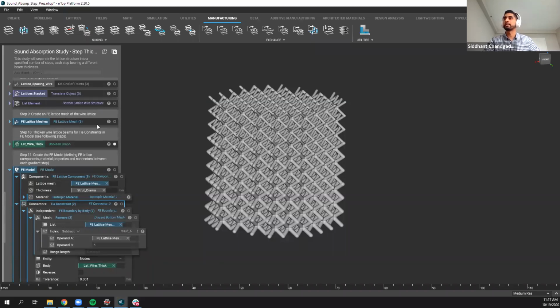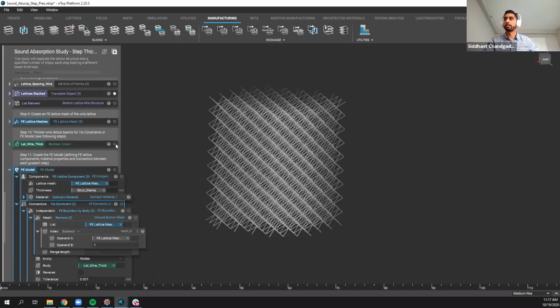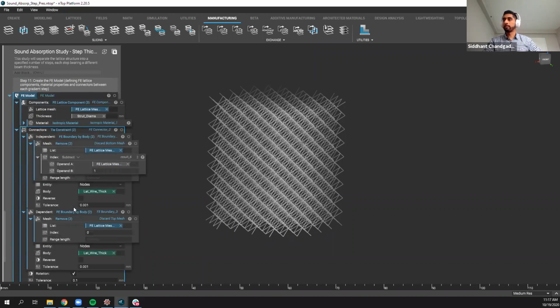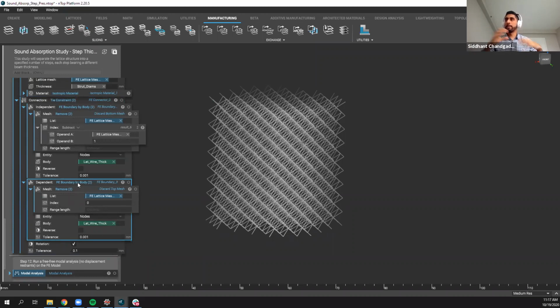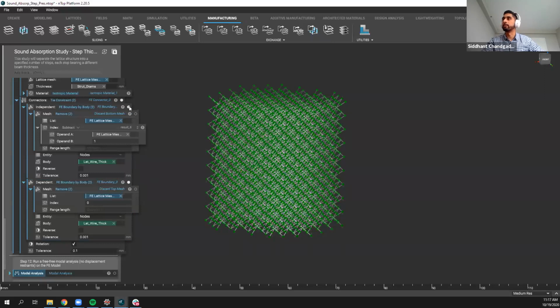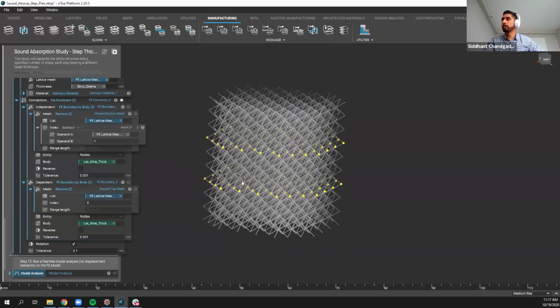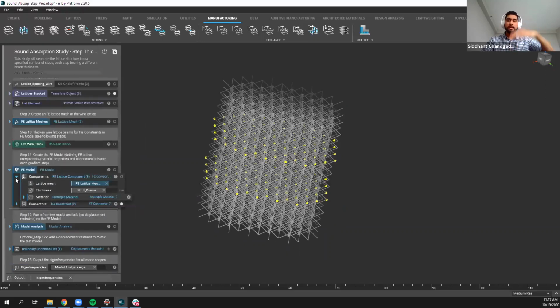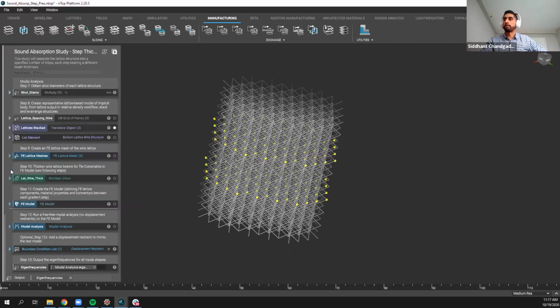We really need some tie constraints since we use this lattice structure that we created, which is the unthickened lattice structure from the original model. However, we needed to tie all of these lattices together. How we did that was to operate through a list, so we could see which lattice structure was close to the next element in that list and essentially create our tie constraints that way. So we saw the intersecting tie constraints, as you can see here, through the yellow dots connecting each lattice. We need that to all connect together so it forms one full model.